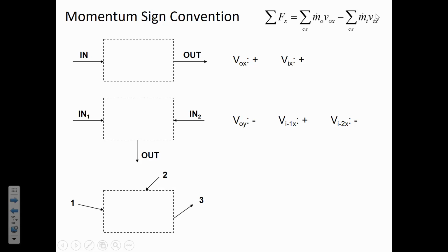All right, so just pay special attention to whether a stream is in or out compared to the control volume, and then whether it will be negative or positive when you substitute the velocity into the momentum equation.